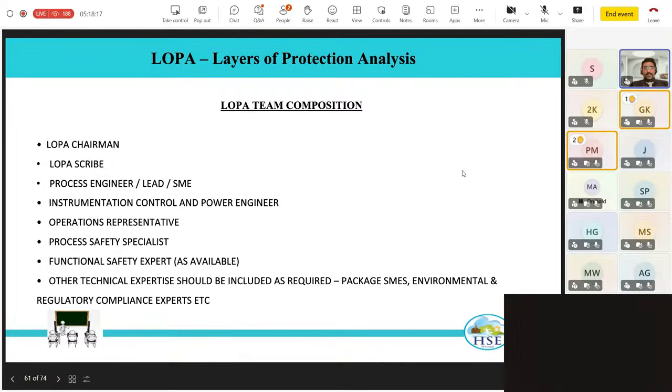Of the many clients I've worked with, most of them, Exxon, Shell, consider 21%. However, BP is one such client that insists that even for fire case, the accumulation be at 10%, which is what you consider for all conventional cases, while for fire in many cases you consider 21%, for all clients. BP insists on a conservative design and would like that accumulation set at 10%.